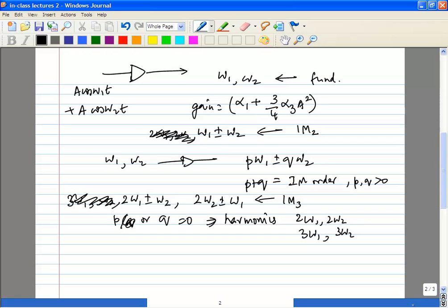Absolutely right. But we are trying to define it for systems where you may not want to back calculate it that way. You want to apply something at the input, find out what you see at the output, and then calculate based on that. We'll look at both ways: calculating from the input output response to get your IIP3, and also applying, let's say, 2 inputs and finding out the harmonics at the output. We'll look at how to calculate using both ways.